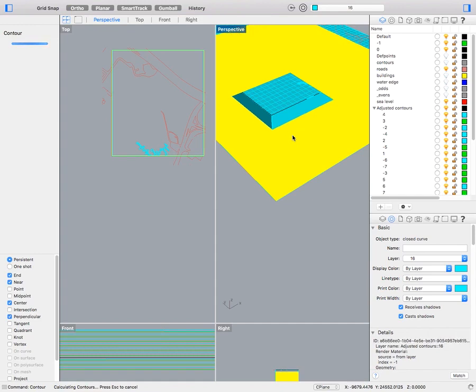Well, you type in contour and then you just tell it which direction you want. You want it to go from top to bottom, bottom to top. It doesn't really matter. And then you change the variable to whichever contour distance you want. So 0.5 meter, meter, whichever.